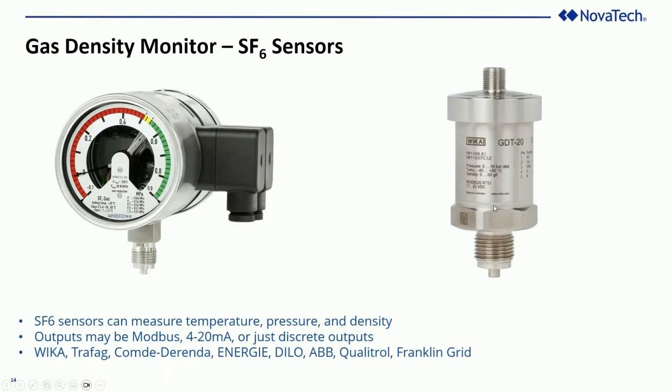The gas density read by these is generally outputted based on the pressure at 20 degrees centigrade. So it provides standardized, temperature-controlled monitoring of the density, so that when the pressure goes up and down because of external heat or cold due to the weather, you'll still get standardized calculations about the actual volume of how much SF6 gas is left.